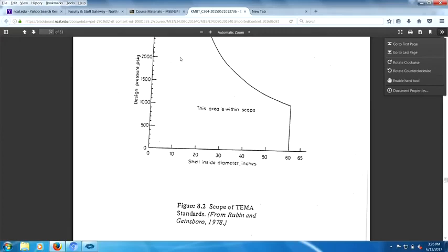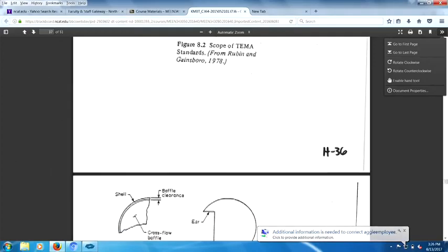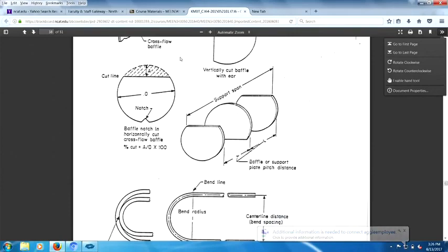So there's three types of heat exchangers we mainly cover, plus the phase change stuff. The upper limit on those other major exchangers is 300 PSI. And you can see you can go to 3,000 PSI with shell and tube. Okay, let's see what else we got.